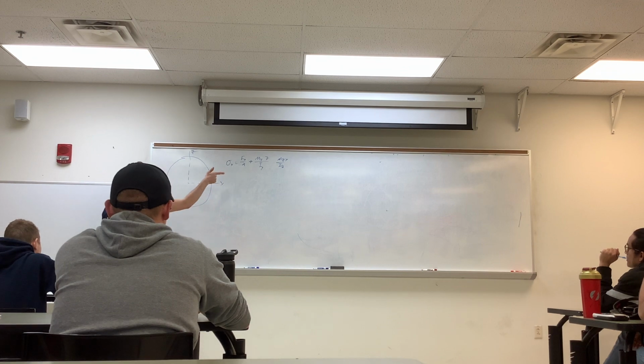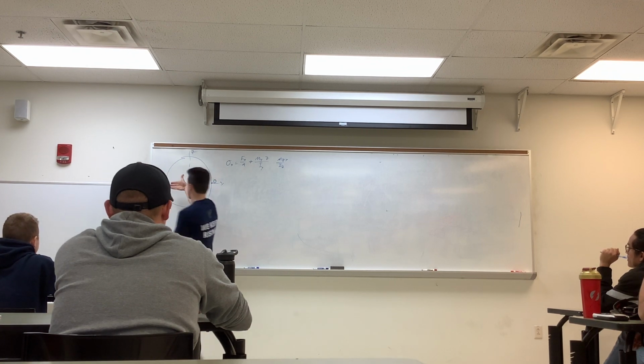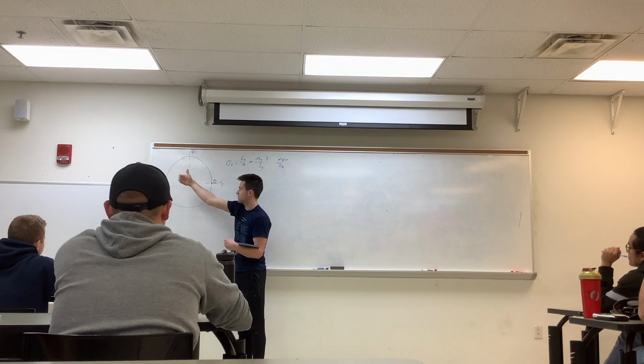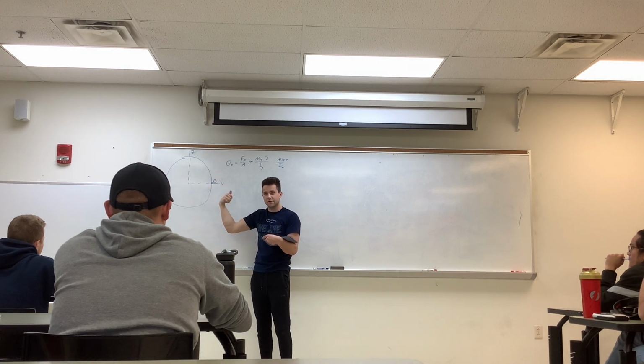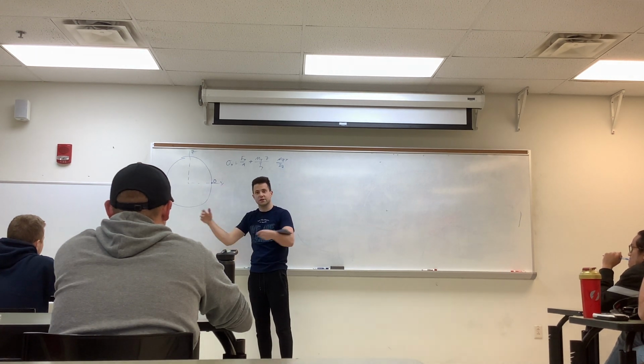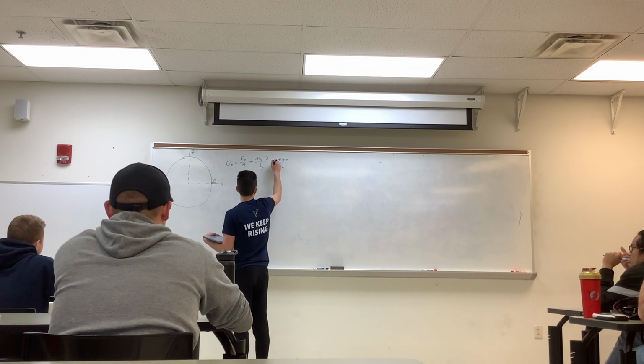Next, we're going to do z. So our moment about the z, thumb upwards along the positive z direction, curling our fingers. This happens to be on the right side of it, where our fingers are curling, so it'll be in compression, giving this value to be negative.